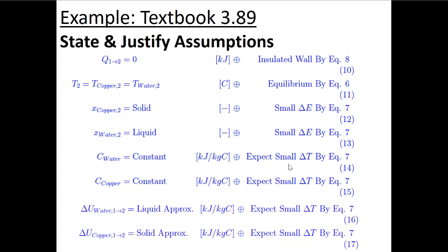That's not too much. If I was talking about a turbine in a jet engine, I might have a temperature change on the order of 1,000 degrees. So I could have a very, very large temperature difference. Because specific heat in real life is a function of temperature, my assumption about constant specific heat gets worse as my delta T gets bigger.